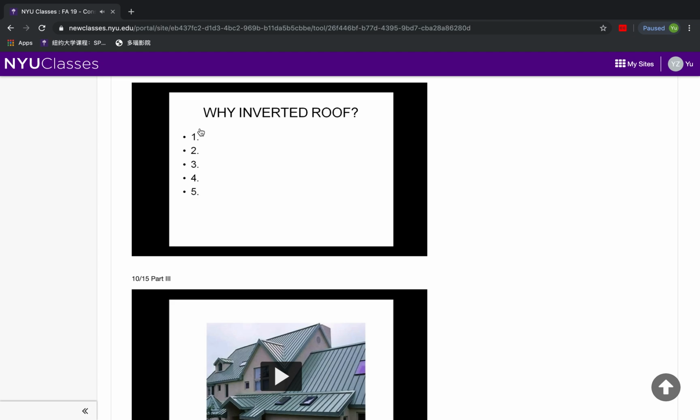And why would you want something like that? Well, again, it depends on where you are. Sometimes that kind of insulation on the top deals with moisture better than the more typical roof arrangement. It could give you a softer walking surface up top where you need it. And this could be a material that's placed afterwards where there wasn't insulation before. So you can put a water barrier and a membrane and then insulation on top rather than on the interior of your building.